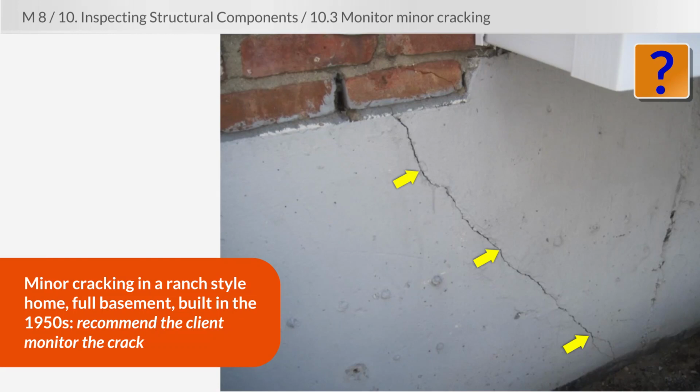I've got the question mark here because you don't really have to say anything about this. This is up to you. Is this dangerous? No. Is it functioning properly? Yeah, it is. The foundation is doing its job. So a lot of inspectors would simply recommend the client monitor this crack.